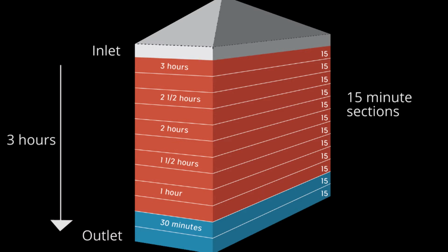The red area is the hot zone, and the blue area is the cooling zone. What's interesting is that many dryer operators make decisions about how fast to run the dryer based on the moisture coming out of the dryer. But we know that most of the drying happens close to the middle of the hot zone. So if you make a change in the dryer discharge rate, it'll be at least an hour in this dryer before you see the impact on the grain coming out of the dryer. For example, all the grain in the cooling zone is going to come out the same no matter what speed you run at. It's too late to change its moisture.